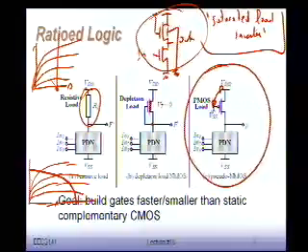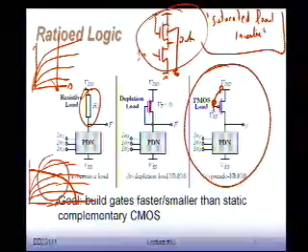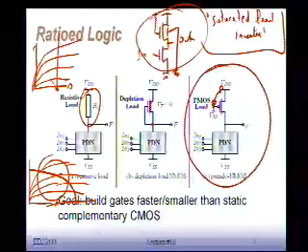Now you can imagine that if the output resistance is actually quite small, when the curve is flat, when you have infinite output resistance, this thing will create a lot of gain. In this region, the PMOS almost looks like a current source. A fixed amount of current pumping into the node, which is nice, right? You start pulling down, and the current stays at the same level.